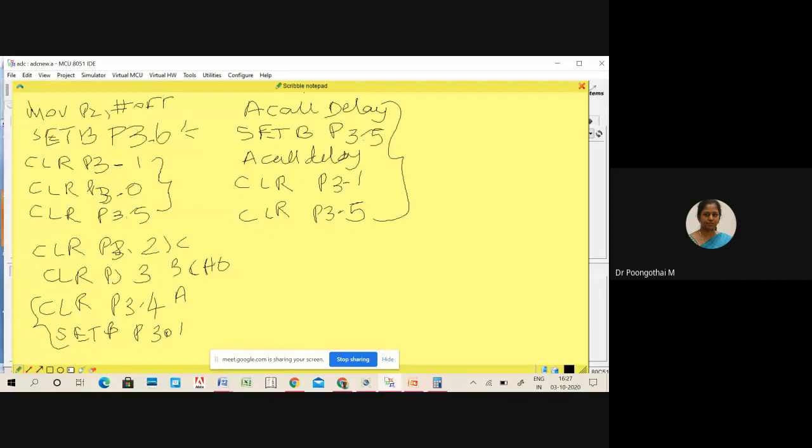So these instructions are used to select your channel and also initiate your start of conversion. ALE high, start high. ALE low, start low. Okay. So what is the next step?